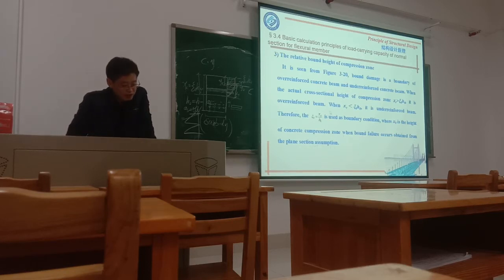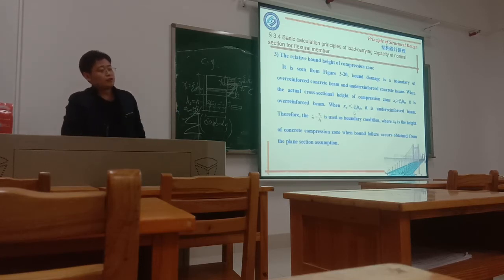So we can compare ξC with ξB. If ξC is smaller than ξB, it is appropriate reinforcement. If ξC is larger than ξB, it becomes over-reinforced.